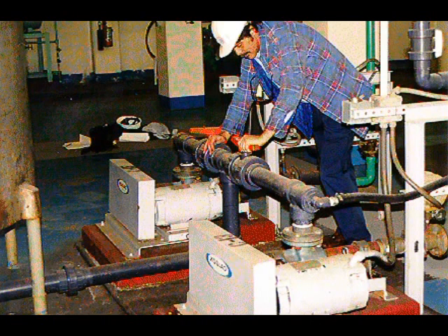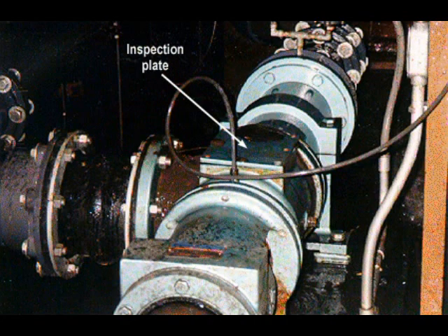Or there may be a loss of suction in suction lift applications. Check that air is not leaking into the suction housing by way of the packing gland. An inadequate amount of grease or low pressures in water flush systems will allow air to enter the suction housing. Also check the piping system for problems. Collection of debris in the suction housing may also stall the flow. In this case, stop and lock out the pump. Drain the suction housing, open the inspection plates, and remove the debris.